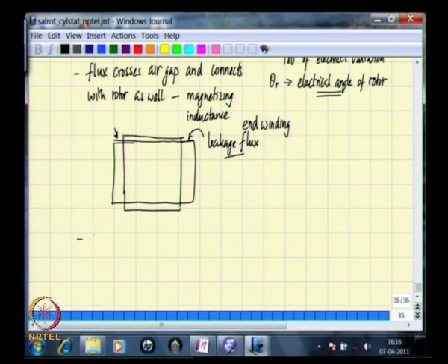The phase winding, so to say, if you consider a particular R phase in a 3-phase machine, is almost usually a distributed winding, which means that the phase occupies several slots, more than one, maybe 2 or more than 2, and the angular separation which is spanned by the coils of a particular phase is then called a phase spread, and it is for such a distributed winding that we really need to find out the self inductance, which we shall attempt to do now.